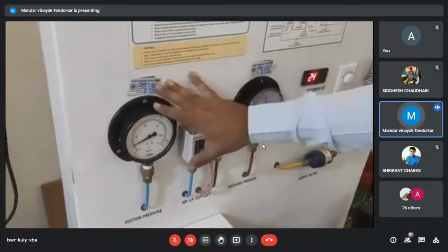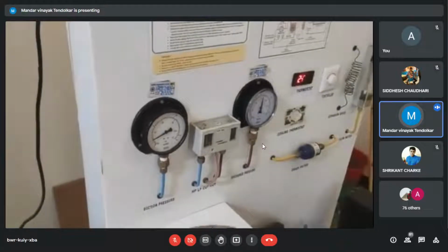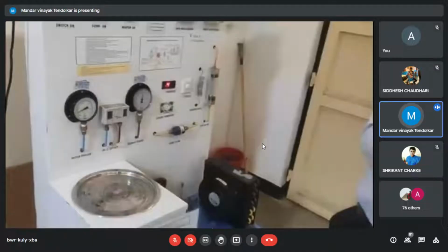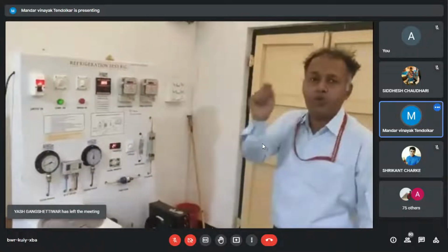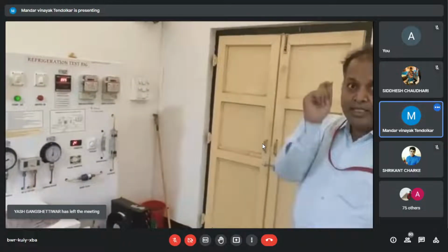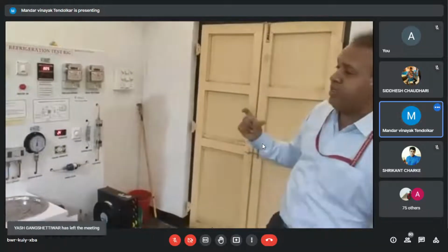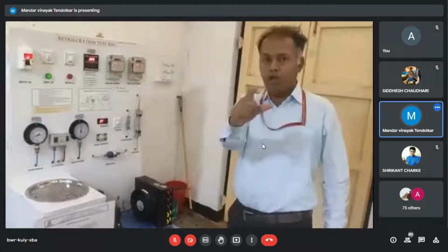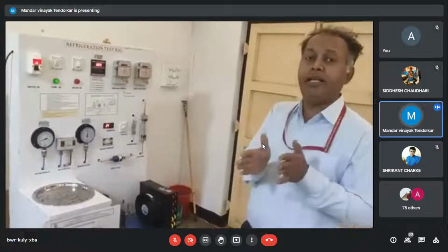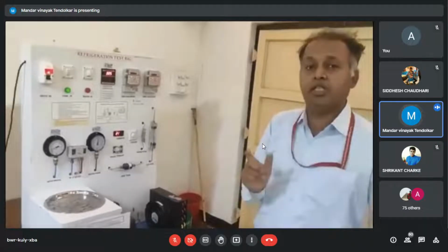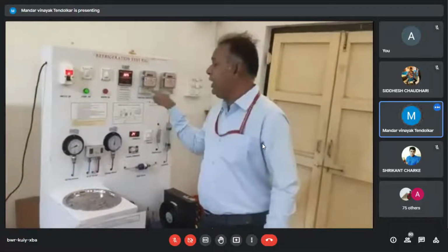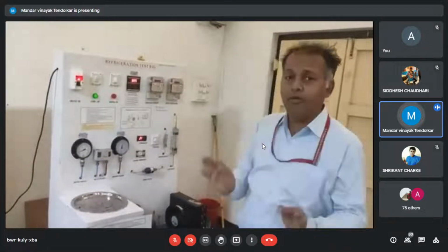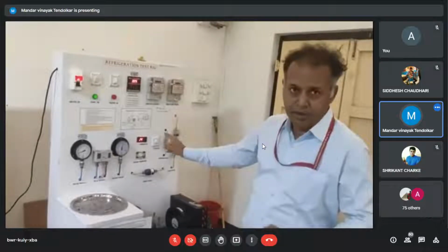So we can note down the suction pressure and the discharge pressure, plot it on the pressure enthalpy diagram, assume it to be a saturation cycle, read the values of enthalpy h1, h2, h3, h4, and this is how we can find the specific compressor work, which is the enthalpy difference across the compressor, and the specific refrigerating effect, which is the enthalpy difference across the evaporator. So getting that enthalpy will help you to determine the theoretical coefficient of performance of this system.